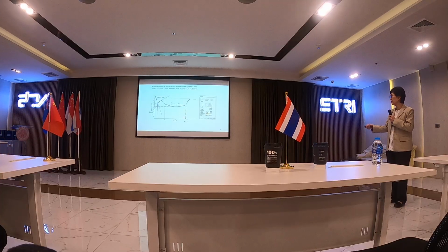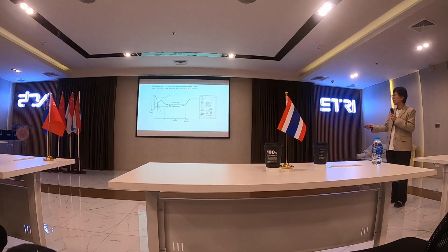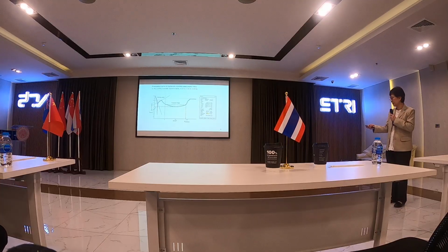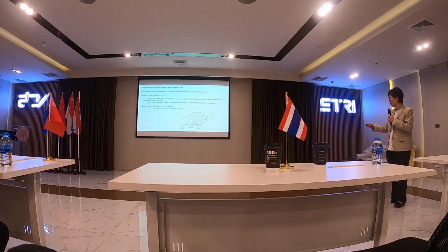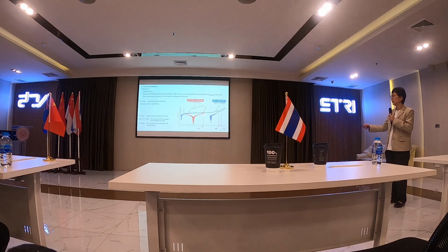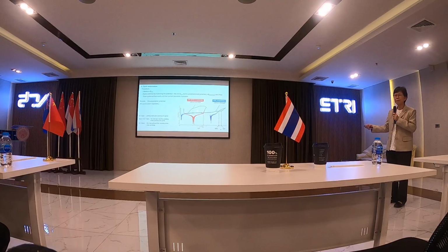And we can see a passive range and then the high passive. That means while the material has a passive film, it still remains corroding at this amount of current. So the next one is cyclic polarization. If we know the pitting potential already, we know that okay, it will pit. If the pit can repassivate, we can use this technique.